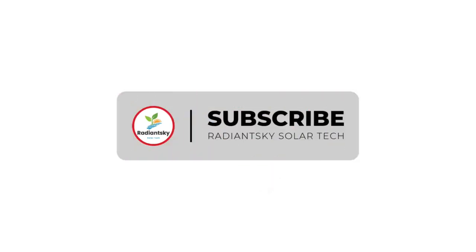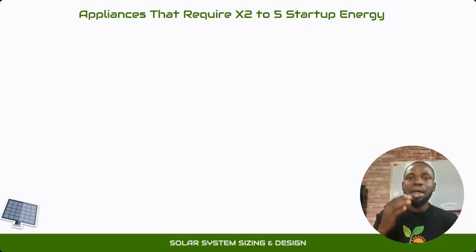So appliances that have this kind of characteristics are appliances that use a compressor, that are motor or transformer based, or have a heating element. So this sort of appliances, you need to consider them when quoting your inverter. You need to give room for their surges.